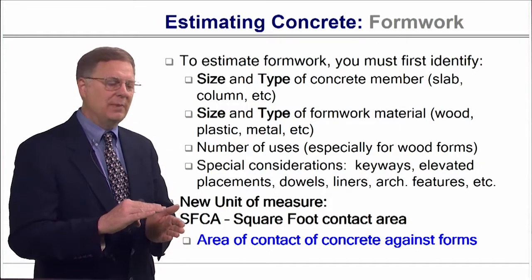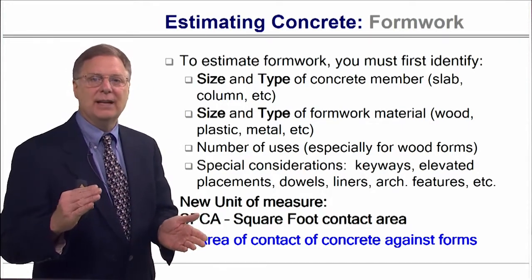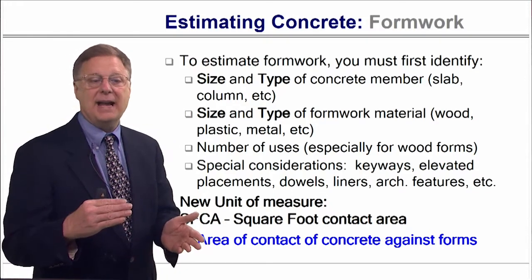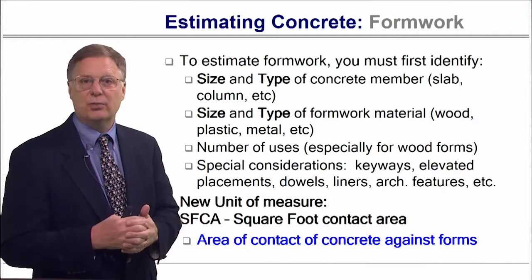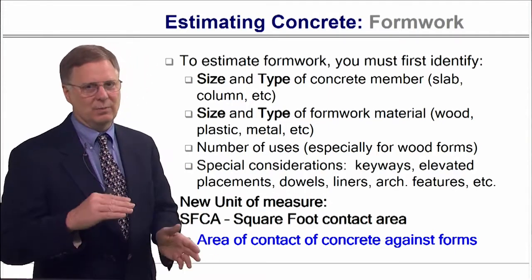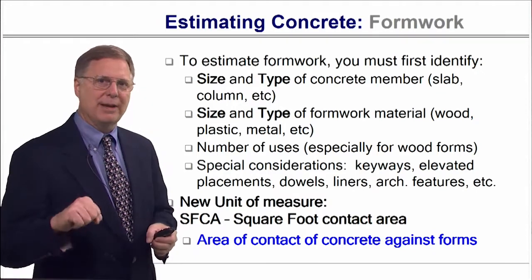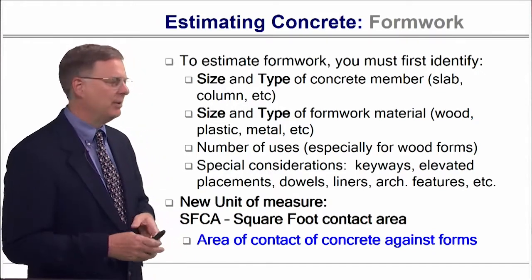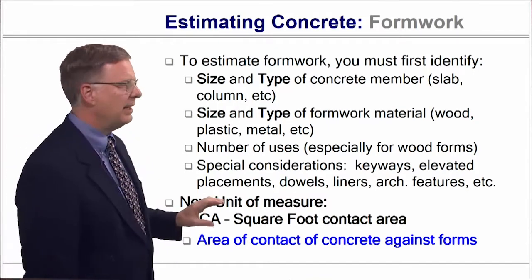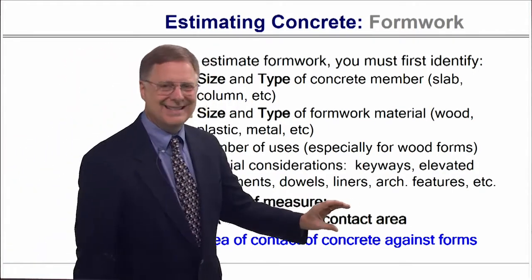Now, you might come in with a regular 2x12 and actually place a piece of concrete at 10 inches, which means either you bury the 2x12, or less likely you're going to try to measure it exactly 2 inches below the edge. So you might have more square footage of formwork, but they are only counting the contact area.